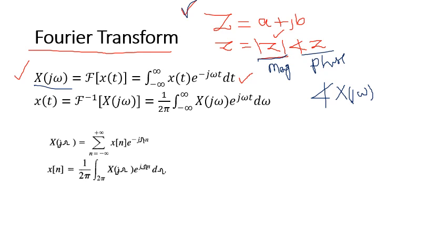So it changes. How is it variable, when will it change? In general it changes with the frequency, right? So that means the magnitude is also variable. In this case, the magnitude will be variable at different values of omega, and the phase is also variable at different values of omega. So the expression for this is tan inverse of imaginary over real, right? Because here the real and imaginary parts are functions of omega, they will change with omega. So the resulting thing will be a graph.